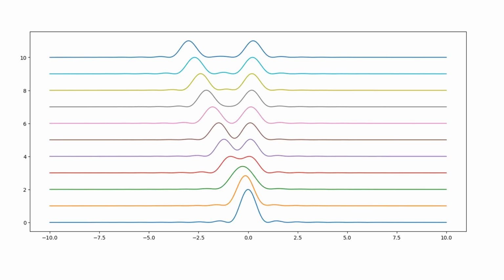What is resolution? It has something to do with the relationship between the estimated object and the embedding space. Here, the embedding space would be along the x-axis, and we're showing the measurements, g, along the vertical axis. This is for 2 point targets that are each resolved as impulse response, which in this case is the unit sinc squared. And what we see in the curves as we go up in vertical position is more and more separation between the 2 point targets.